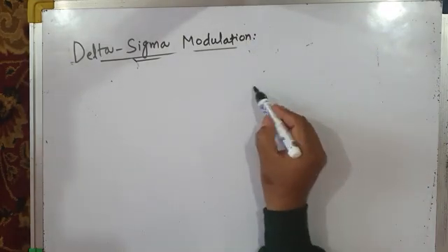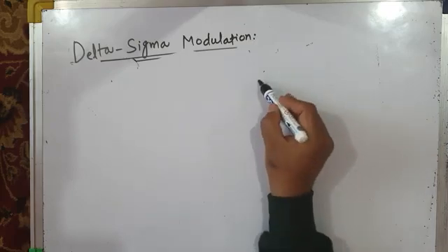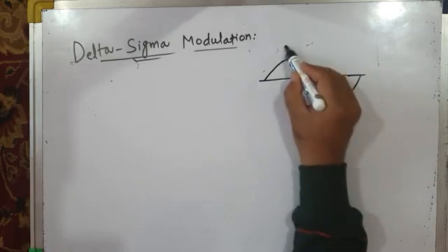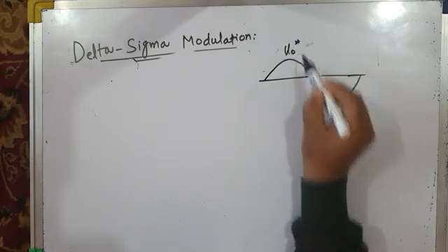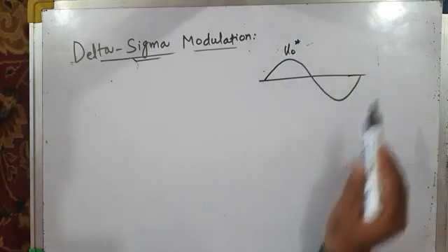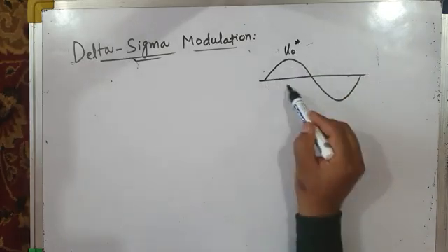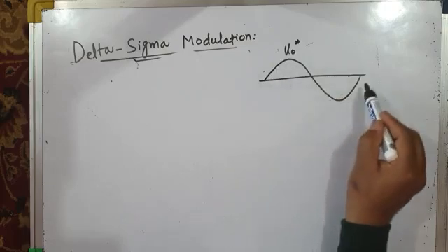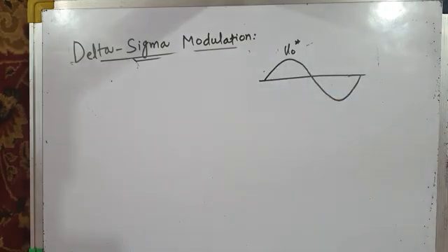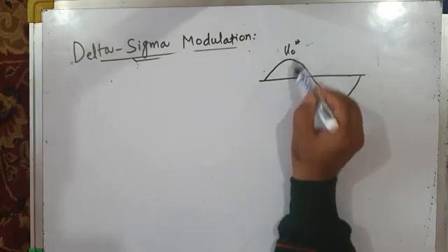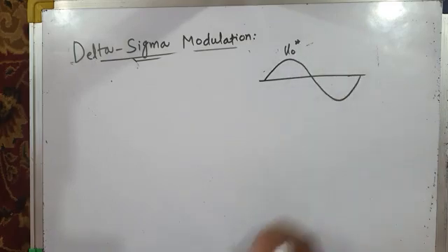So what I want, instead of controlling the load current, I want to control the load voltage. So I want my load voltage to be sinusoidal like this. So I want my load voltage V0 star to be sinusoidal like this. Say this may be the load voltage of a particular phase. Say phase R, then phase Y and phase B will also be similar but 120 degrees phase displaced. Let's take a particular phase. So I want my phase voltage or inverter output voltage to be sinusoidally varying like this.